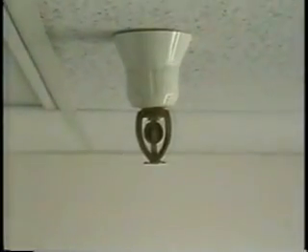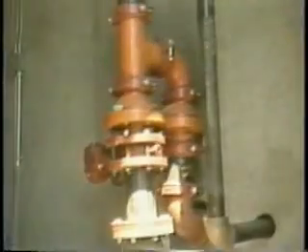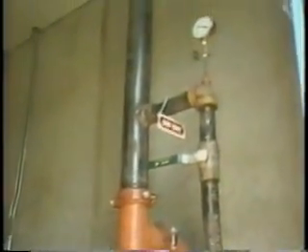Standpipe kits made up of a hose, adapters, and valve keys can be made up ahead of time, and generally are, with those departments who frequently work with standpipe systems. Pumpers can also be utilized to supply water volume and pressure support to building sprinkler systems. Sprinkler systems consist of plumbed piping throughout a building with heat-sensitive sprinkler heads.